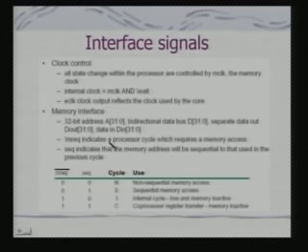What is important and interesting to note is the memory interface. It provides a 32-bit address, it has got a bidirectional data bus and separate data out and data in. So, you have got in fact these 3 buses. So, you can have a first data transfer, and there are various signals which indicate the kind of processor cycle which is going on.